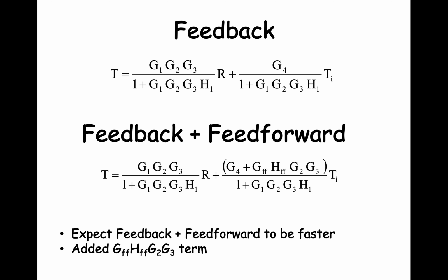It's commonly done using computer simulations, which are followed up with field tests. Feed-forward control also commonly uses a lead-lag transfer function within the feed-forward control element. We have not discussed the lead-lag transfer function so far in this class, so we will simply use a steady-state compensator term, KFF, for GFF.